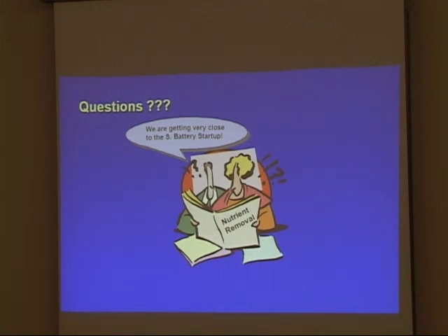There is some work that has to be done anyway, so they can identify it. In aeration tank number 3, there are some couplings that have to be repaired. Obviously, the same thing with the final settling tanks. We want to make sure that there aren't any problems with the north battery final settling tanks with the structure beneath the surface.